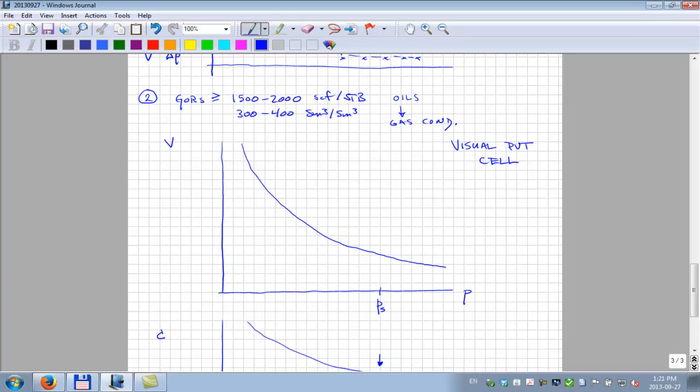In general, you don't look for that first little drop or bubble. Instead, what we do is that we measure, as a function of pressure, of course, total volume, and we look for the liquid volume. Of course, by difference, you have the gas. And for an oil, I'm going to draw the oil volume in the case so basically you won't know what it is above the saturation pressure, right? But if it's an oil system, I'll do that in green. What it'll look like is this.